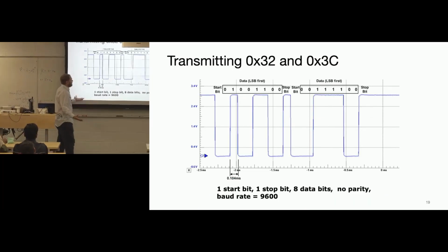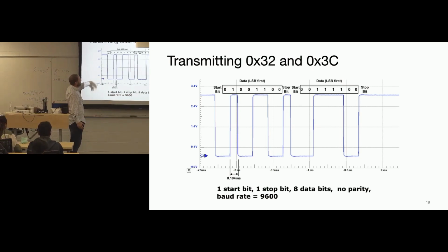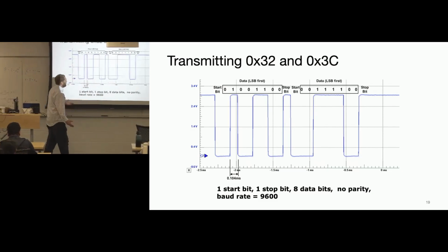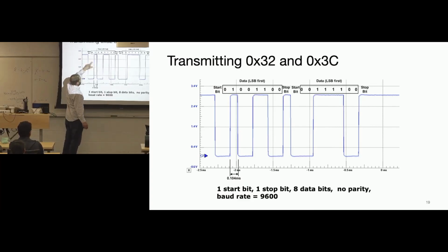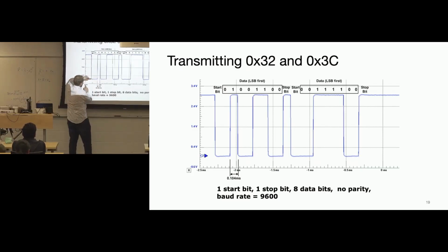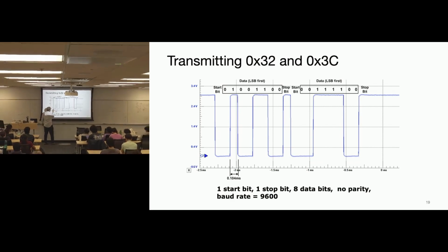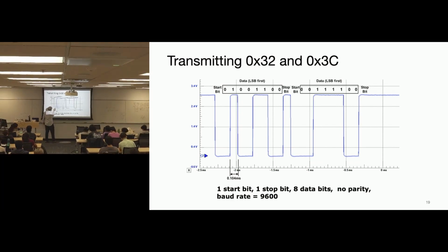Your job, after going through lab and working on serial interfaces for a while, is to be able to understand the UART protocol. Here we have, say, a transmit pin, transmitting to the cellular device. It starts up high, and we see a low sequence. There's a start bit, held low for a period of time. You would have to already know your baud rate, and you could calculate, using the time scale here, when half of it was over, and then a full 16 oversampling here, and then calculate right here each one of those things to recover the bits.